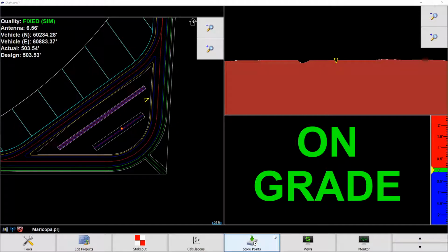This will give you a surface that you can then use to compare the existing ground to the proposed grade to verify your and/or the engineer's earth moving quantities. This would also be useful for tracking and billing time and material jobs. When the job is complete, you can use the topo feature to record and then hand in professional looking, accurate as-builts with all of the material quantities and done directly from the data collector.